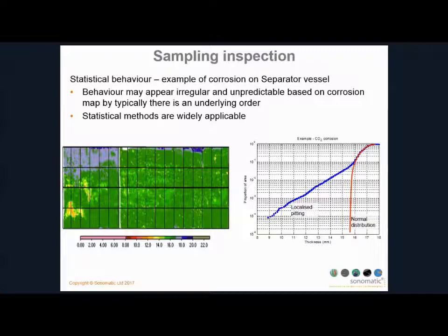Now the interesting thing here, and what lets you establish that it's an exponential distribution, is that tail, when plotted on a log scale, is pretty much linear, and that indicates that it is exponential, and because of that it's also indicating that there is predictable behavior. That kind of situation is widely seen with equipment suffering corrosion in service.